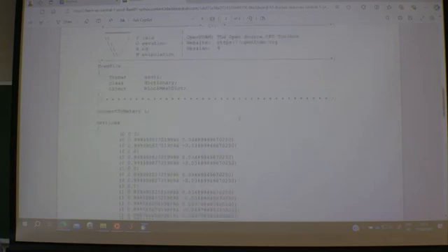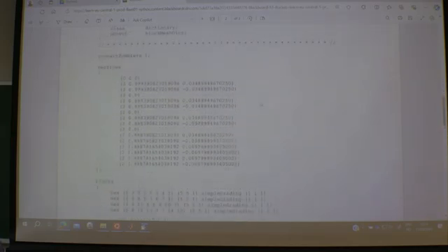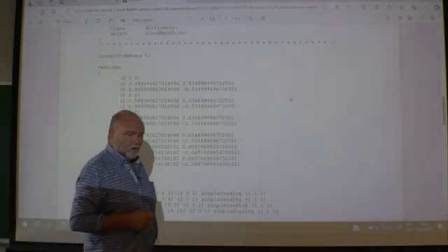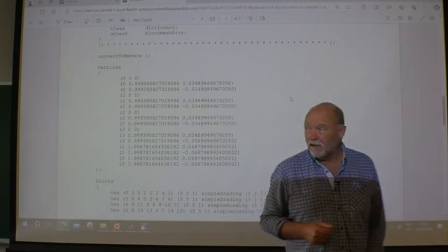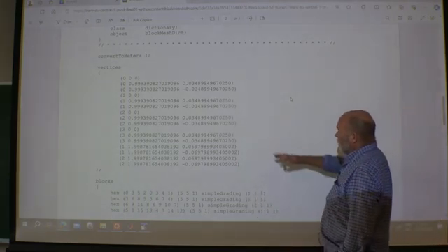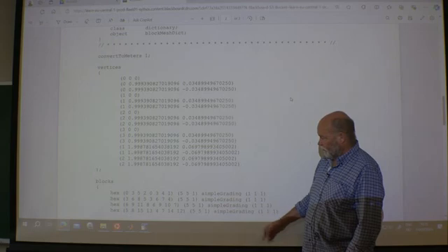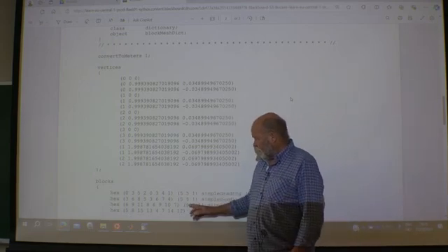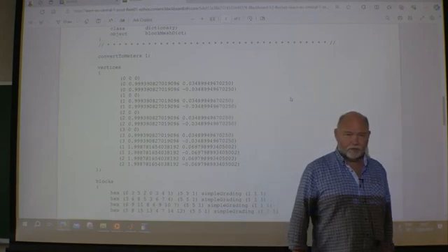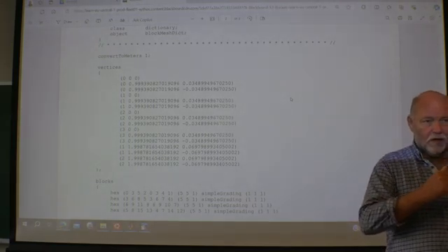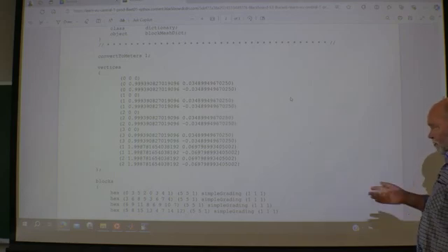Let's have a little look at such a mesh system when we come to what's called a wedge. This is a piece of cake when you want an axisymmetric 2D simulation. I specified some corners, and here I now have 4 different blocks. Each block has 5x5 cells in, say, the radial direction and the axial direction. Nothing happens in the theta direction.